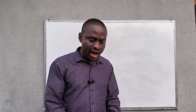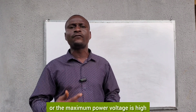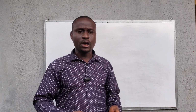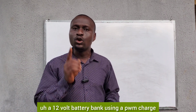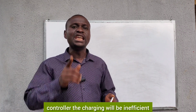Why? For a 320 watt panel, the open circuit voltage or the maximum power voltage is high. Some of them are about 36 volts, some even up to 40 volts. So if you are using that high voltage to charge a 12 volt battery bank using a PWM charge controller, the charging will be inefficient.